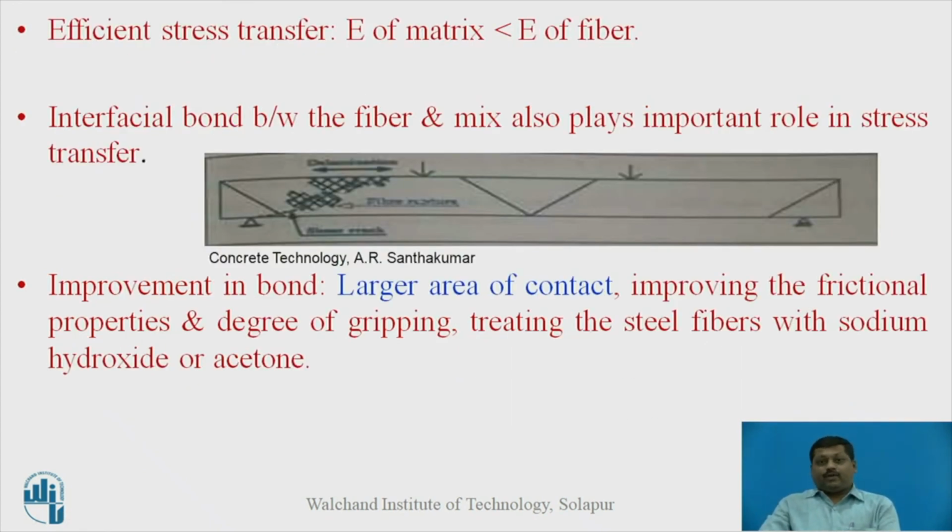Now next is for efficient stress transfer. This is an important factor. For that, Young's modulus of matrix must be much lower than the Young's modulus of fiber. This is an important factor. Next is the bond between fiber and the mix. Now you can see this diagram. This beam, which is a flexural member, so load is applied. Here one crack is developed, and this is the fiber mesh. So this crack is arrested by the fiber.